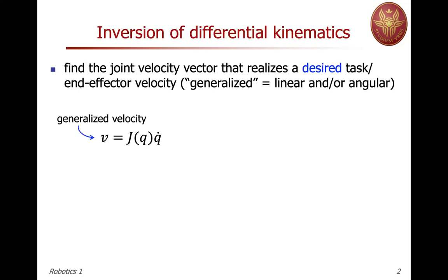So this is the relation that we will use. Now, this looks like the geometric Jacobian. It could be the analytic Jacobian, the geometric Jacobian. We don't care, so I skip the subscript and just use Jacobian collectively. The generalized velocity is in the task space, q dot is the unknown, and we are in a given configuration.